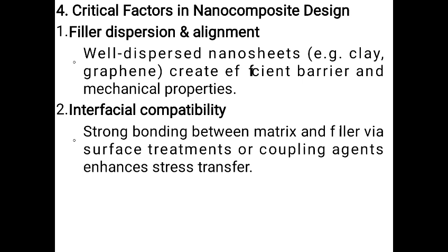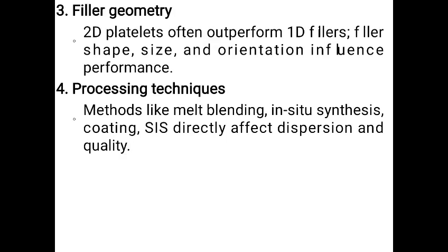Then critical factors in nanocomposite design: filler dispersion and alignment. Well dispersed nano sheets, that is clay, graphene, etc., create efficient barrier and also has good mechanical properties. Interfacial compatibility: strong bonding between the matrix as well as the nano filler via surface treatments or coupling agents enhances better stress transfer.